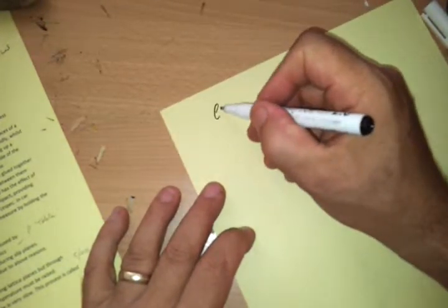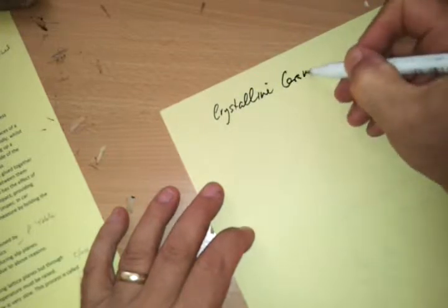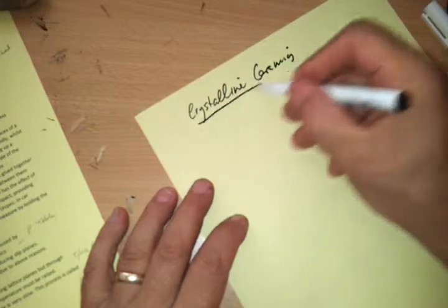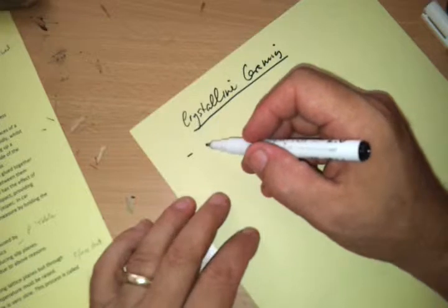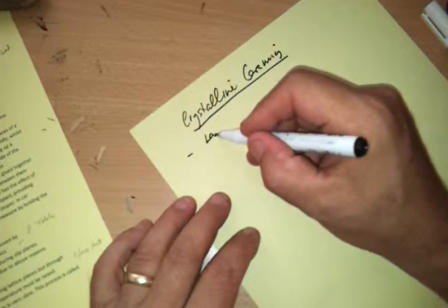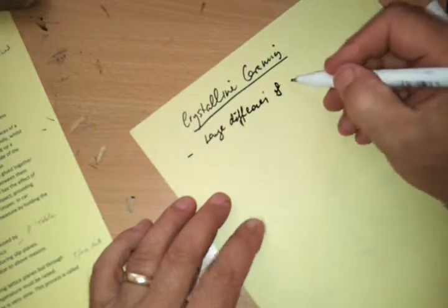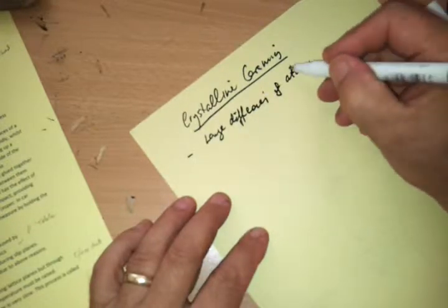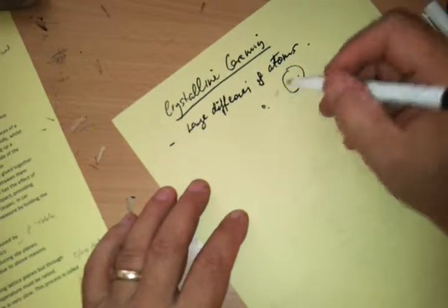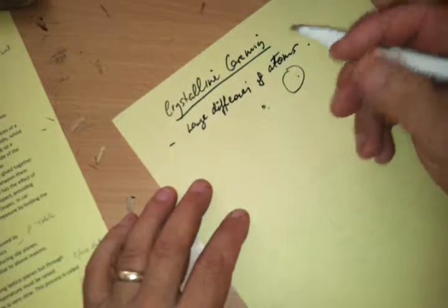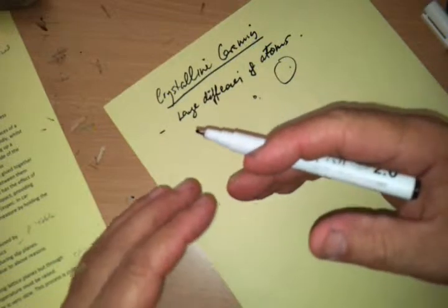These are ceramics that do have a regular repeating three-dimensional structure. Crystalline ceramics are very brittle, and the main reason for that is there are large differences in the sizes of the atoms in ceramic compounds. You saw, for example, silicon's very small, oxygen's quite large, and frequently metal atoms are bigger and the silicate is smaller. So that means it's much more difficult for there to be slip planes.